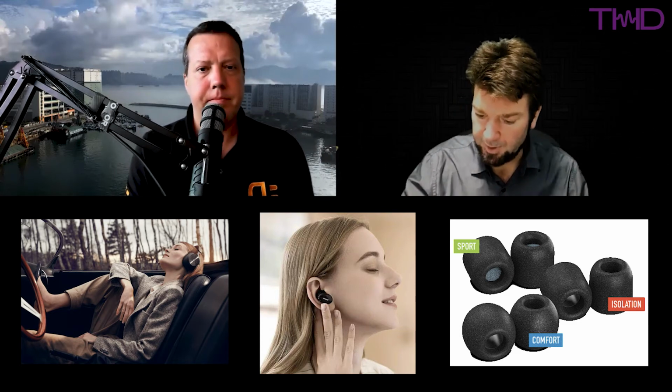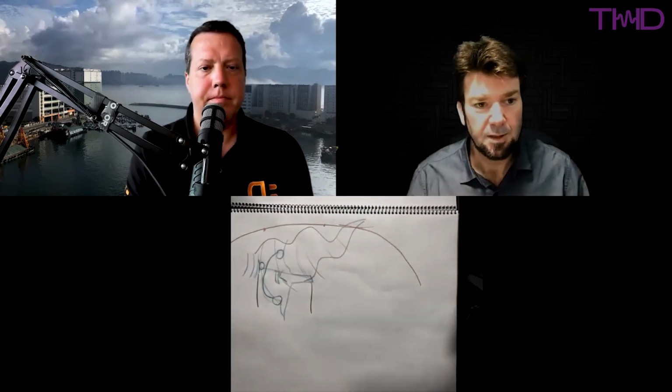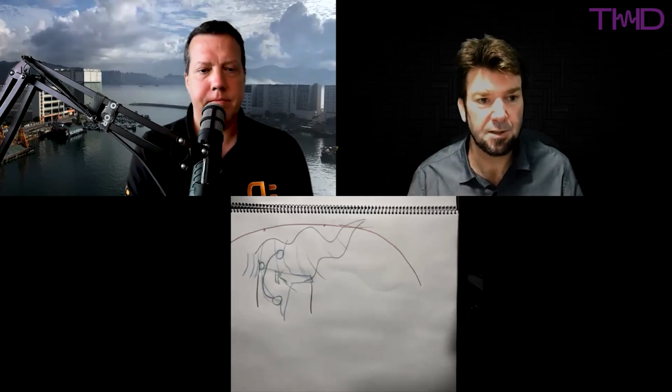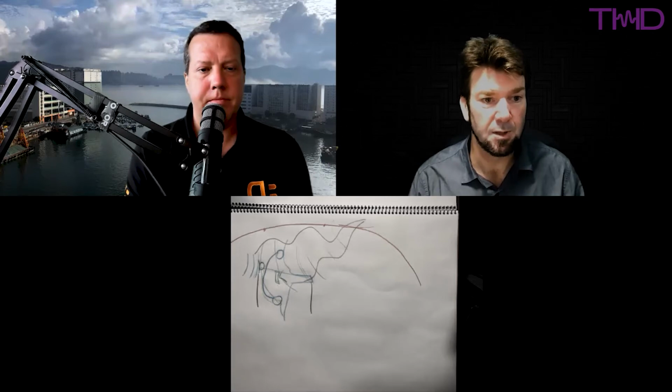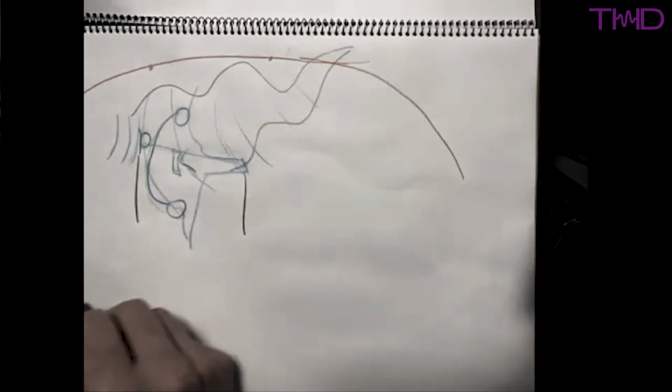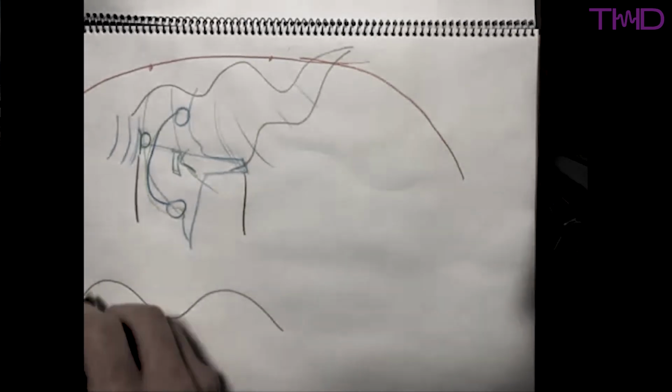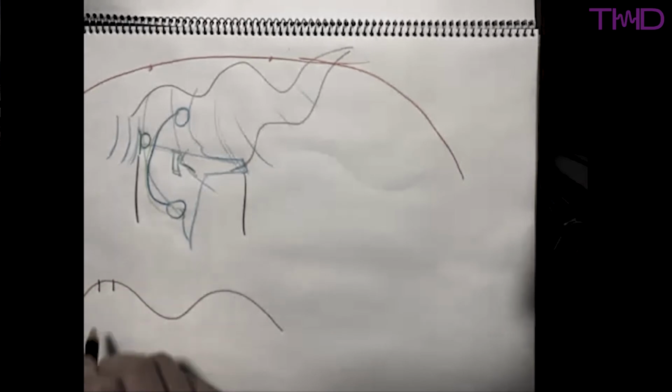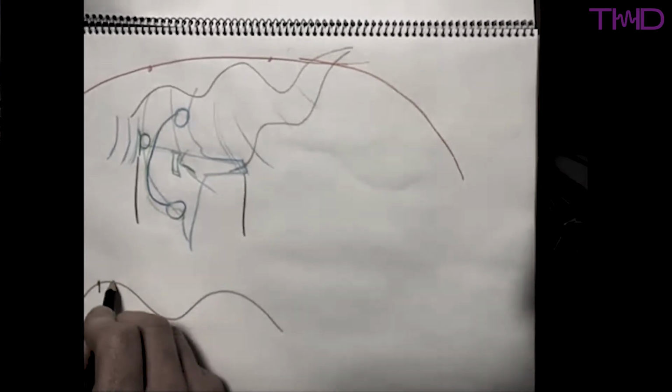What's the distance between that microphone and the ear canal? As that distance gets larger, the high frequency that you can go up to gets lower and lower. So if they're very close together, and you have some waveform, and the two things are this distance apart, the difference in the pressure of that wave at those points is really not much at all. It'll work fine.